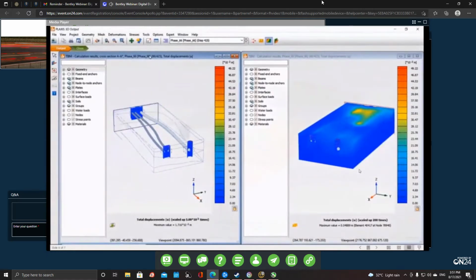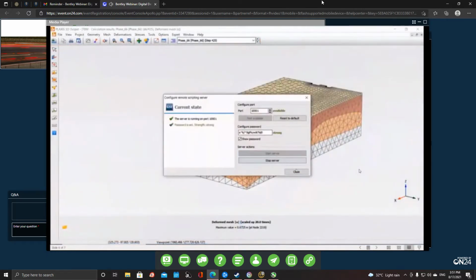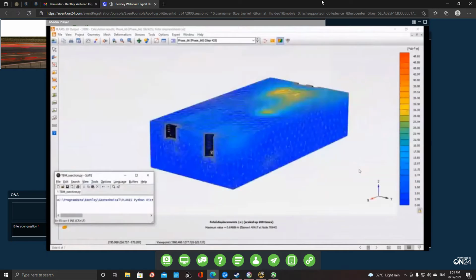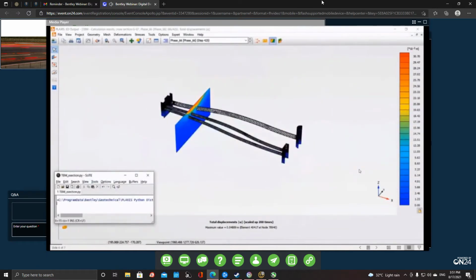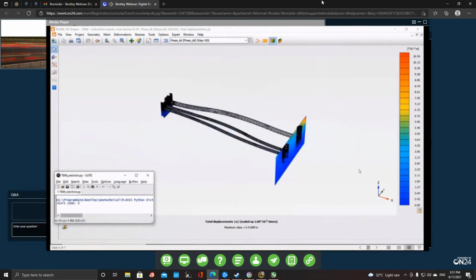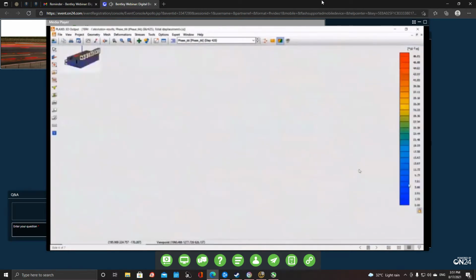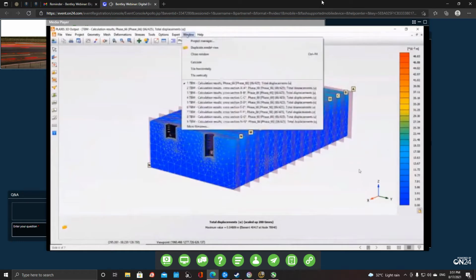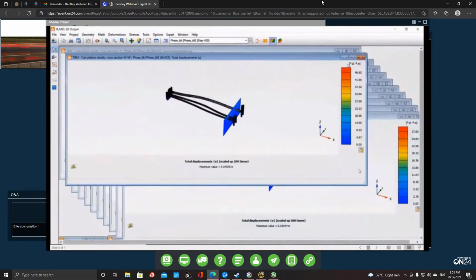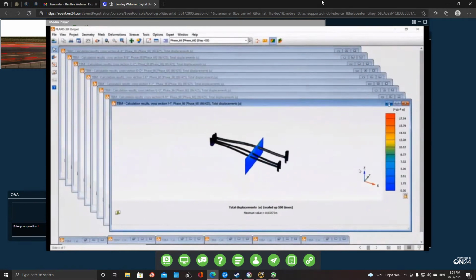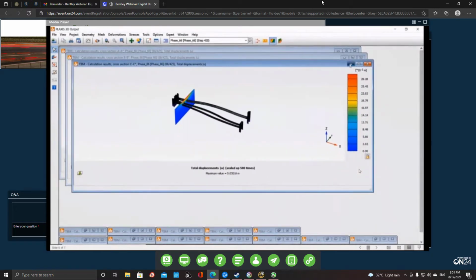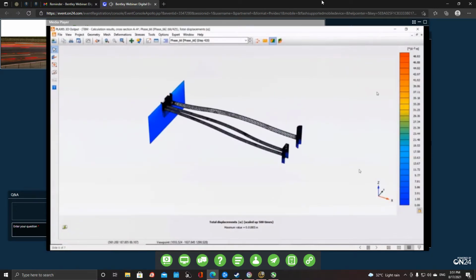In practice, TBM tunneling induced ground settlement is mostly estimated based on empirical relationships or guidelines. Those mostly provide site-specific characteristic parameters for prediction of ground settlement in terms of volume loss and trough width. However, empirical methods are unable to consider the supporting effect of the TBM shield in the calculation of volume loss, and consequently, a relatively conservative value of volume loss is adopted in ground settlement control.